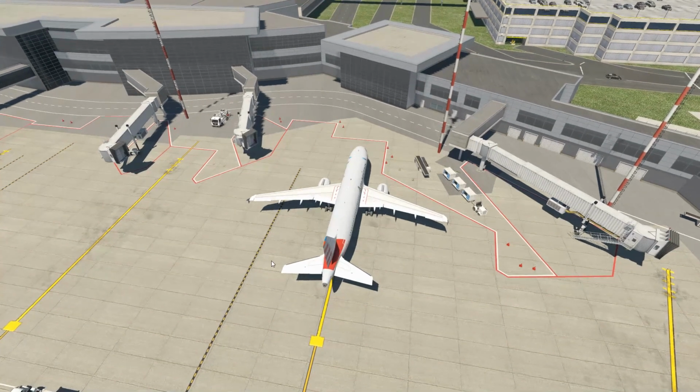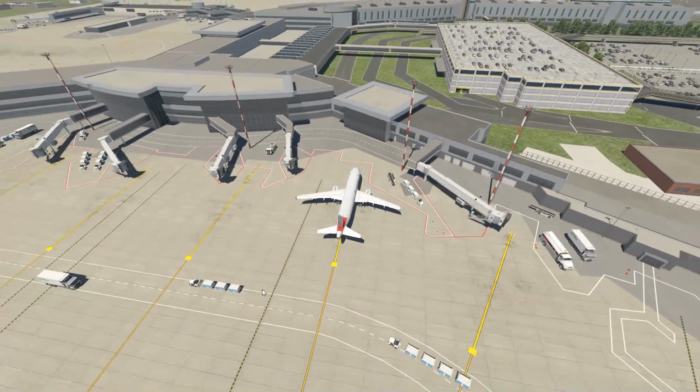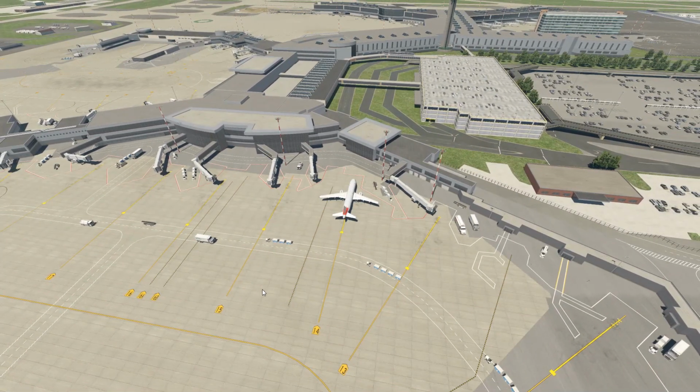So it actually doesn't take long to put in these gates. You can see all the gates are numbered here. So pay attention to that, because if you want to put in a whole bunch of gates, then pay attention to the numbers. You can load the overlay editor and X-Plane, have them both open at the same time, and it's best to have the overlay editor on one screen and the plane on the other, and working in conjunction with each other, you can really put in the AutoGates in a hurry.